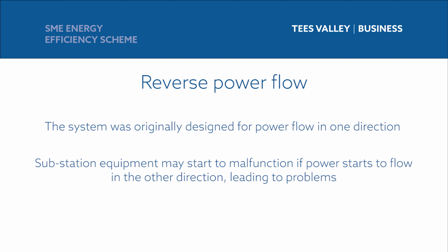Reverse power flow. Because the system was originally designed for power flow in one direction, substation equipment such as online tap changers can malfunction if power starts to flow in the opposite direction.